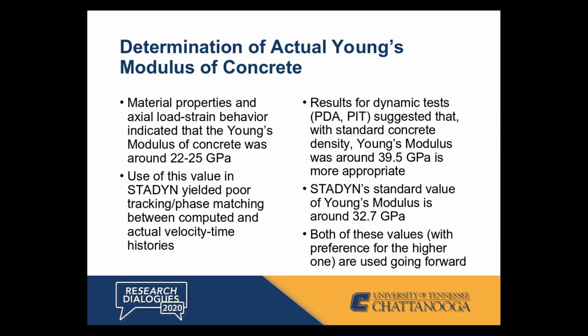In STADYN, we start with a force time, and we measure the velocity time at the pile head that comes back, and then compare it with the original. When we did that, what happened was that we had phase issues, we had other issues, we had some magnitude issues, and this suggested that the material properties that were given were not applicable to what we were actually doing during pile driving.